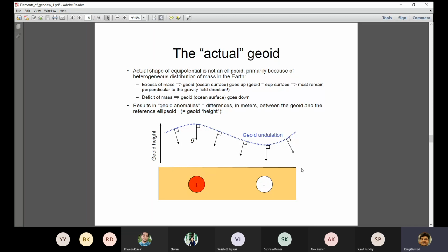The conversion I explained in the last class, that there are various models available. One such model for applying the geoidal undulation on your study area is EGM08. When you have EGM08, that means you know the undulation information above the ellipsoid. So when you remove these undulations above the ellipsoid, you get a particular orthometric height.